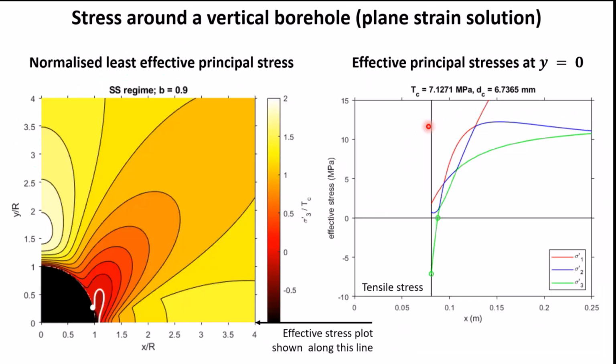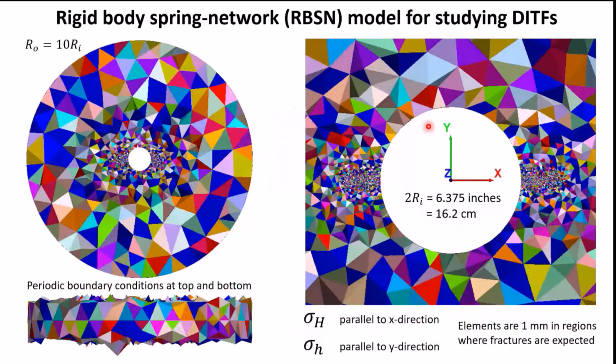So generally, you need a very fine mesh to capture the stress field at the crack tip. That's the first challenge. The second challenge is you need regular remeshing to model the crack propagation paths. Right? And based on my understanding, there is no commercial code for crack propagation analysis due to this challenge.